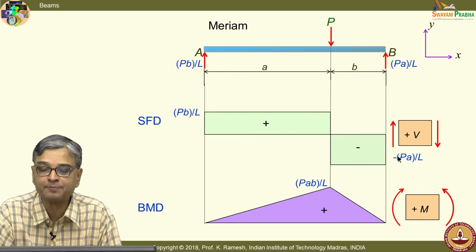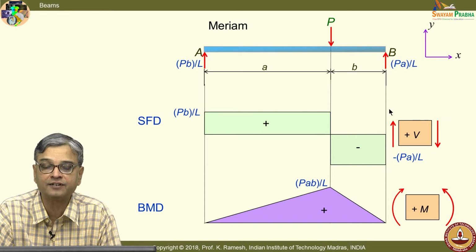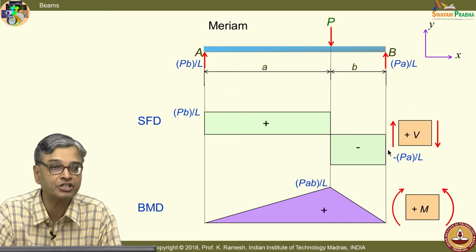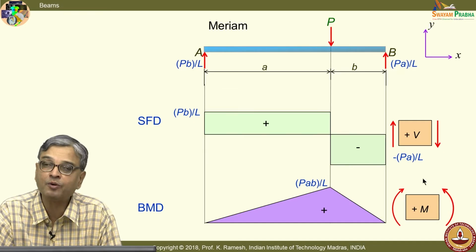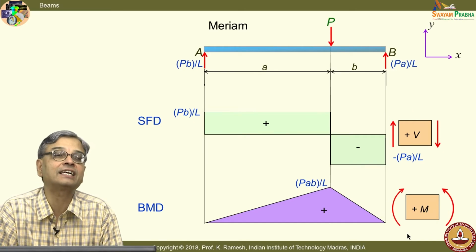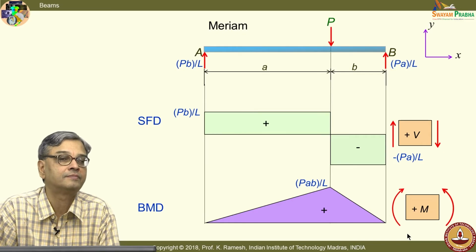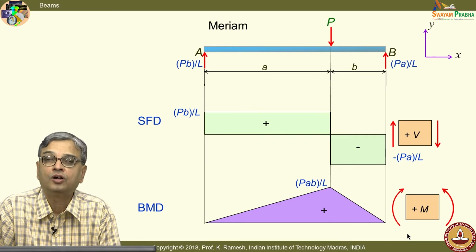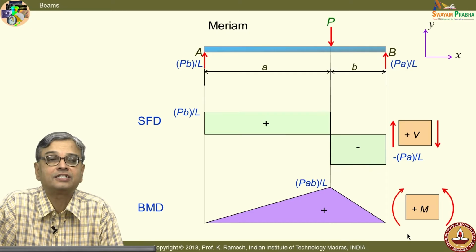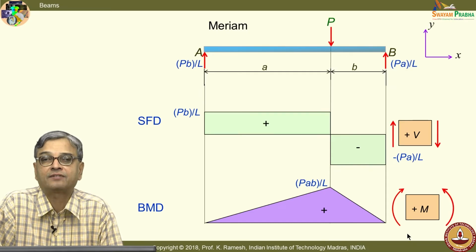Another very important aspect is you should always associate the shear force diagram with its sign convention and bending moment diagram with its sign convention. Do not put shear force diagram and bending moment diagram without any sign convention.